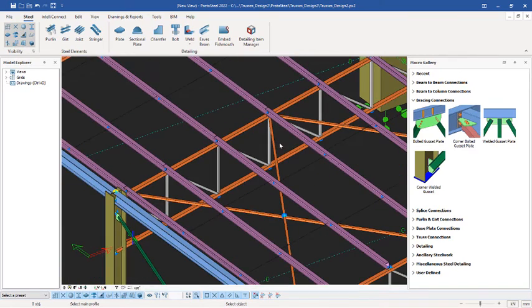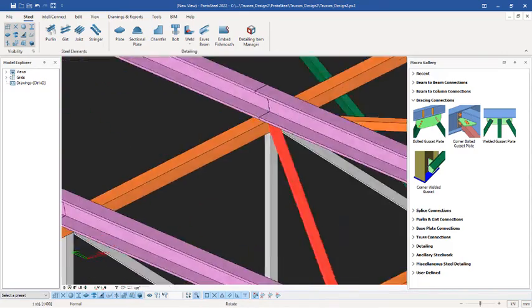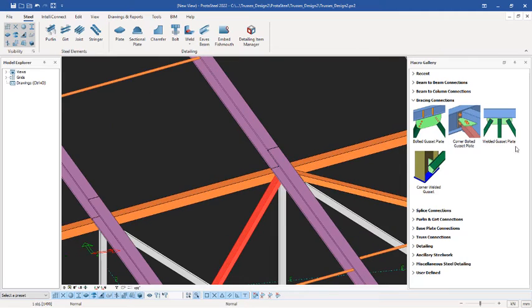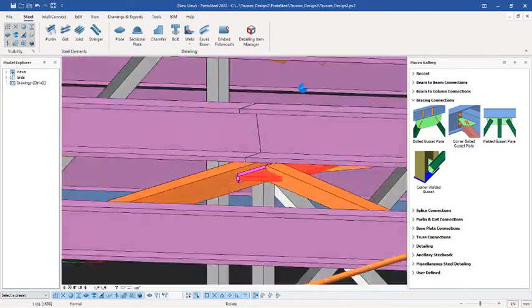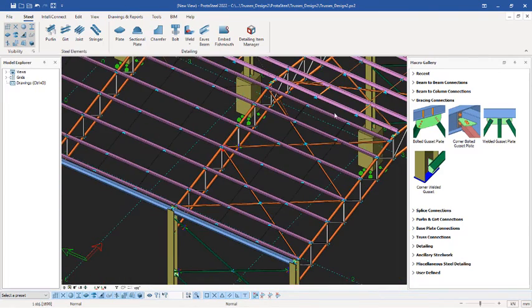roof brace. Okay, this roof brace, if you zoom in closely, you will use just the same method. What you do is select this member, select these two just like this, right click to insert that. So you can see the gusset, the way it looks, very modern, it's not clashing with anything. So this is how you actually fix all your gusset plates successfully.